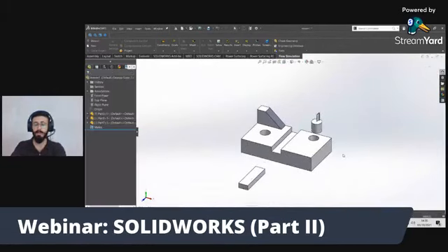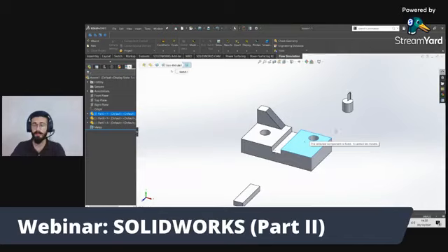Now always remember, whenever you are importing parts in the assembly, the first part you import is always fixed, it is not movable. I will show you. If I click this part, I can move it anywhere in my assembly workspace. But I can't move this part, because see the notification: the selected component is fixed, and it can't be moved.